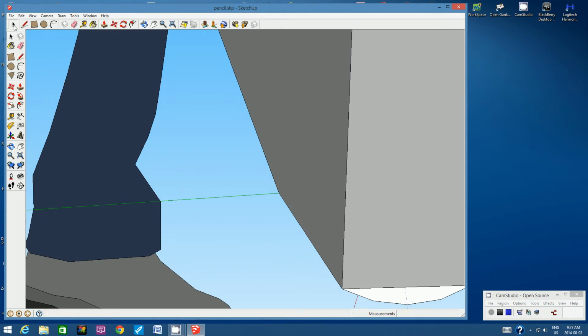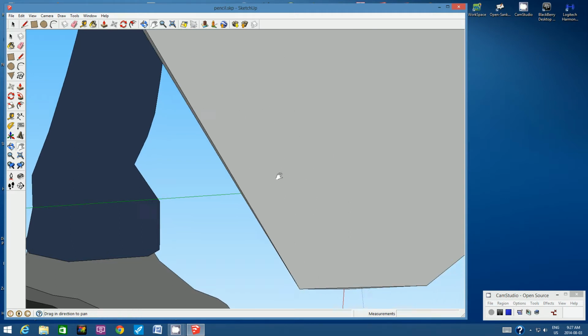I'm going to click on the selection arrow tool, click on that edge, right click, choose explode curve. I'm going to right click, choose divide, make it into 4 segments. Deselect, make sure you deselect. I'm going to click on the move tool and then move each point down. So I hope you're getting the hang of it. So I'm going to go a little bit faster.